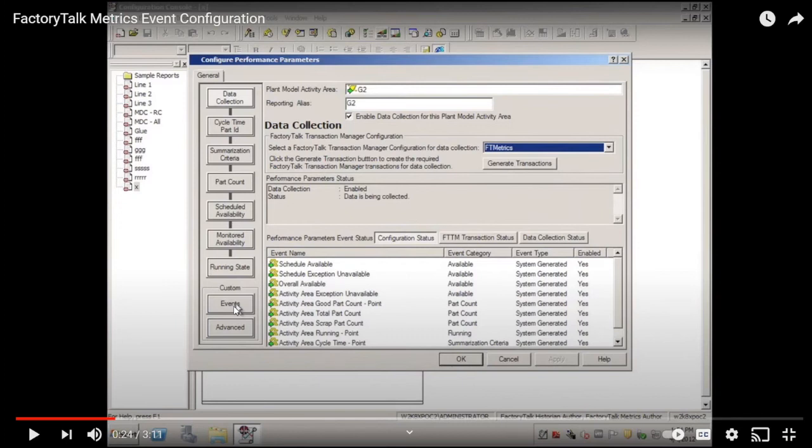That's when you want to start to track downtime, so obviously alarming would probably be one way to track downtime. You probably want to limit it as you're developing your system, maybe 10 alarms per work cell type of thing, but obviously machines can have hundreds of alarms.